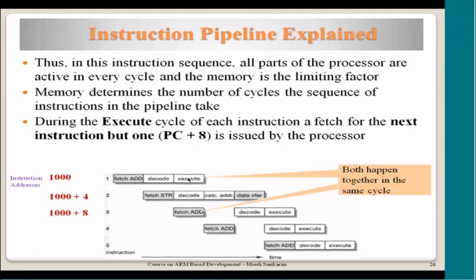So if the programmer assumes that when the add instruction or whatever is getting executed, R15 is pointing at its own address or the next instruction, it is not true. R15 will be pointing at the second instruction from the current instruction getting executed. So any dependency on R15 in the assembly code needs to comprehend this pipeline effect during the programming. When we talk about some instructions and their impact, we will be touching upon this.